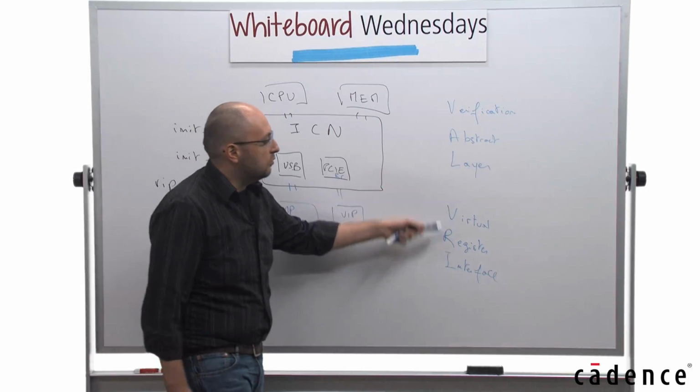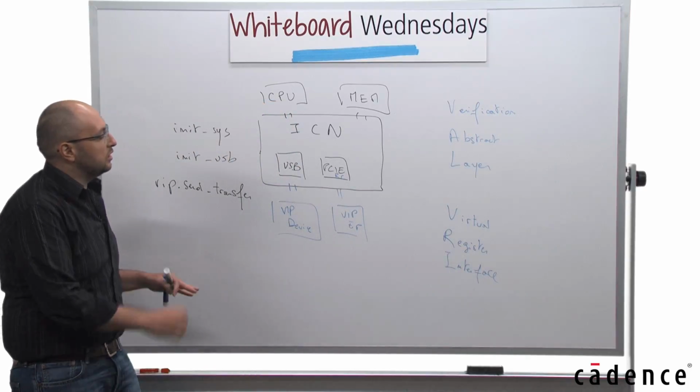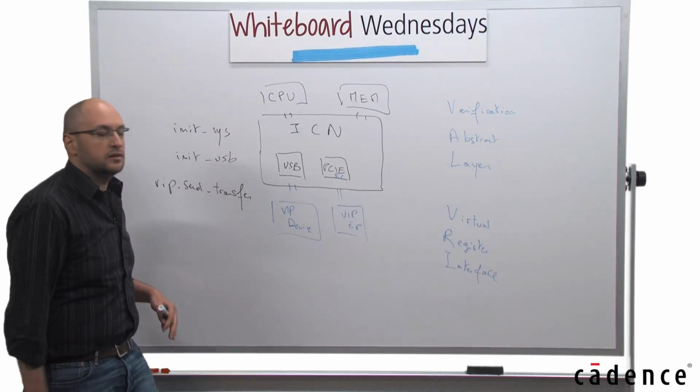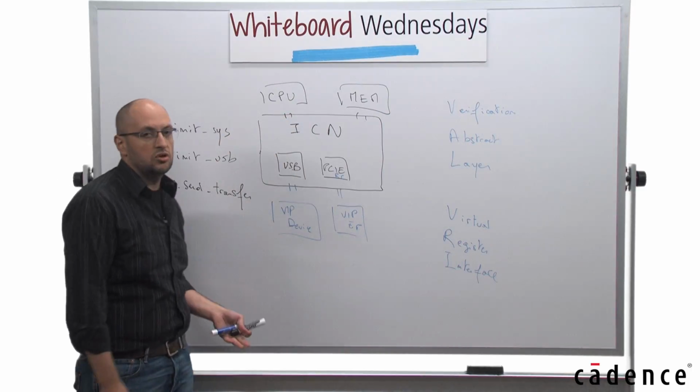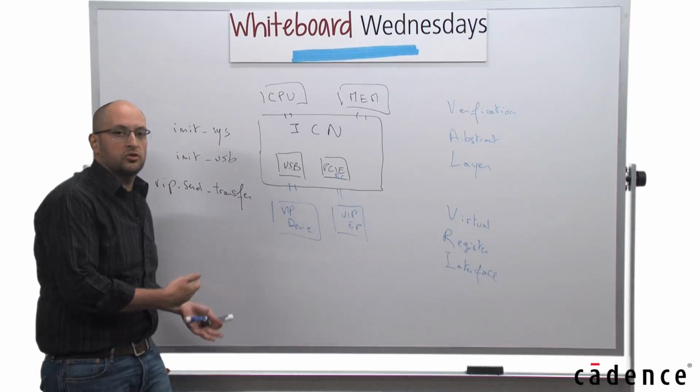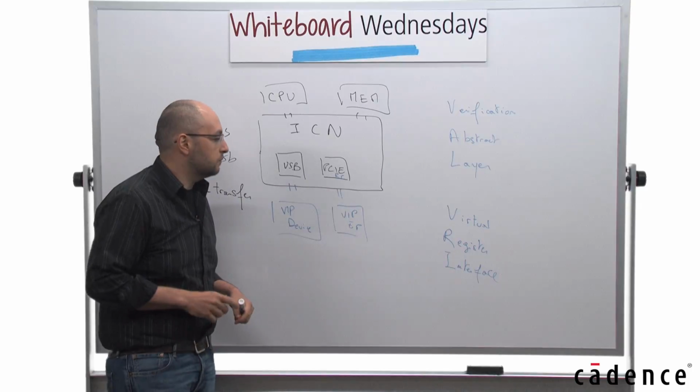And this sublayer, the register interface, exists because we are splitting all of the commands into register accesses so that you can see them passing in the interconnect, and the verification IP is memory mapped and recognizes the order that comes to it to send the proper command at the proper time.